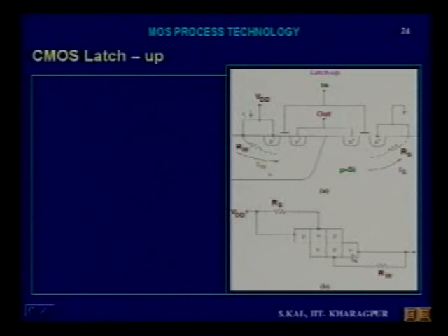So one N region is common, which is the PNP base. This well is the PNP base, P, N, and P. And this N region also acts as the NPN collector. Isn't it? So that means one base is common. This N region is basically the well region.